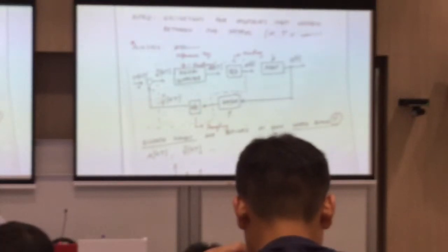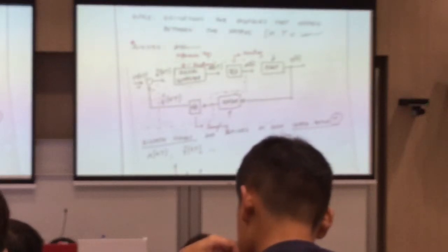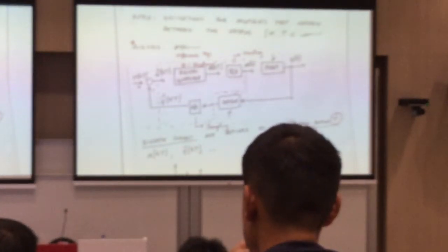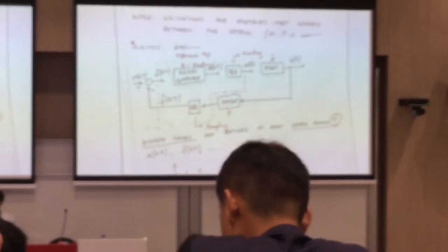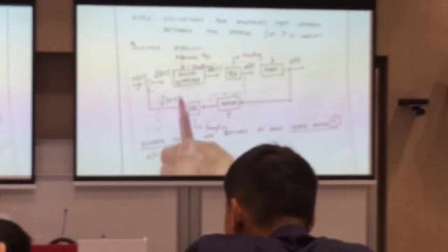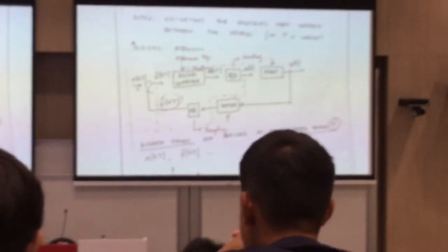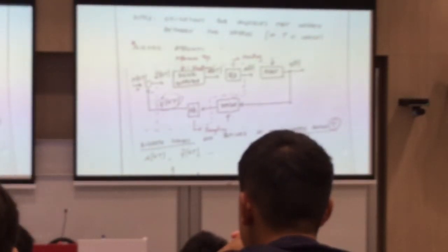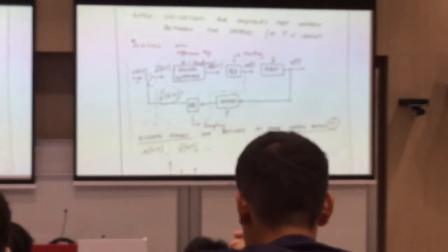Then the differences between digital and analog: first of all is the signal. Instead of an analog input signal, you sample the input and have an analog-to-digital converter, so your input signal becomes digital. Then at your control part, instead of a differential equation, you have a difference equation. Instead of the Laplace transform, you have the z-transform. So your controller becomes a digital controller.